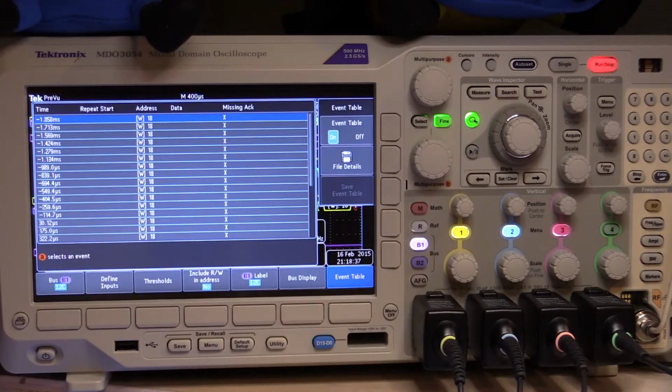Okay, just checked on the Arduino website and just had a look at some of the code, and yes, true to form, the address is actually 98 when you look at it on a pure binary aspect, but the libraries take whatever address you give it and they shift the value left 1 bit so that it makes room for the read-write bit, which is normally just toggled on the least significant bit of the address, so that the chip knows whether it's being told to read or write.